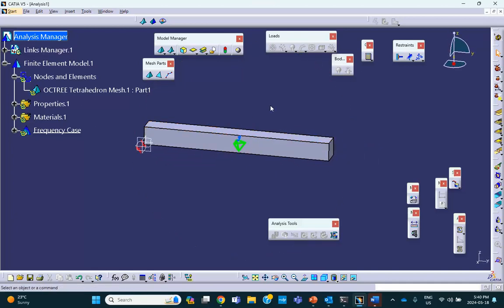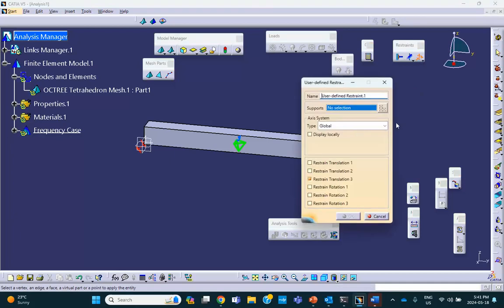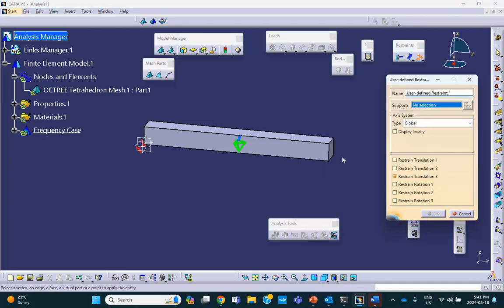Okay. And then this edge is allowed to move horizontally. Horizontally means in direction Y because it's on a roller. So you click on that, select that edge, but say you cannot move in the direction Z or X, but you're free to move in the direction Y because it's essentially a roller.